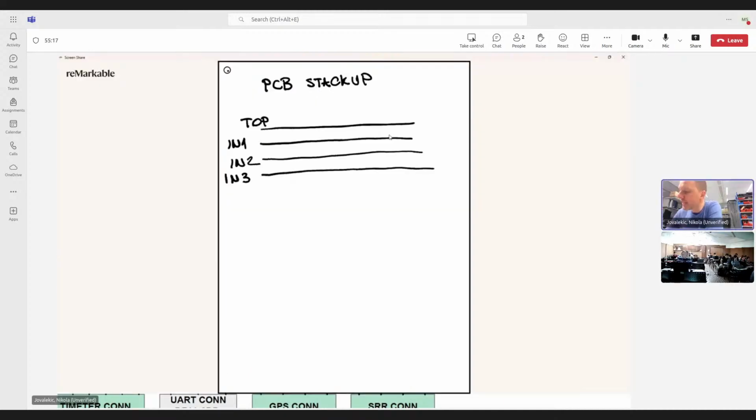And then you want to say that, for example, if we have a component here, which is the clock generator, I would just write oscillator, then this is a pin that we go for, and this is a ground layer, and this is a ground layer. And then we can go in this layer here, using a so-called stripline structure, and then coming here, the sample analog front end to the ADC, and coming to the pin, if I properly understood.